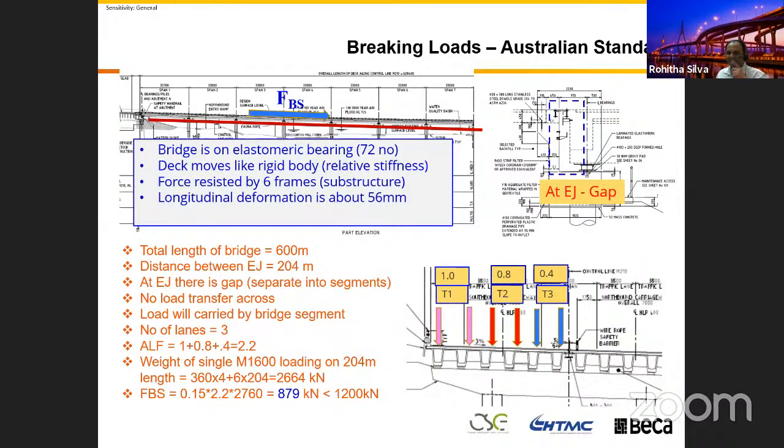So sometimes the structural engineers, I noticed the people were arguing about this 2-3 millimeter. You didn't consider the substructure deformation. That one is so big. That is going to have significant effect because they never do bridge analysis and the design, how significant that number is going to be, and they keep arguing. There's an effect that not that significant. It's very different if you use the fixed pot bearing in a box girder bridges. That is a different story.